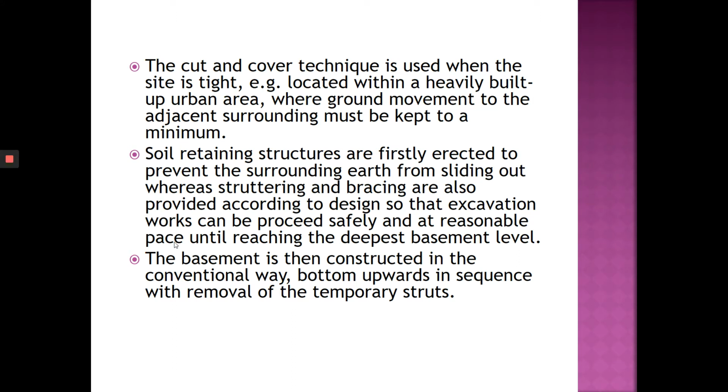Okay, so you can do your works, but there is something that retains the soil from coming in. So you can actually do work without worrying of the risk. They reduce the risk doing this, at reasonable pace until reaching the deepest basement level. The basement is then constructed in the conventional way. It's the same as open cut just now. Bottom upwards in sequence with removal of temporary strut.